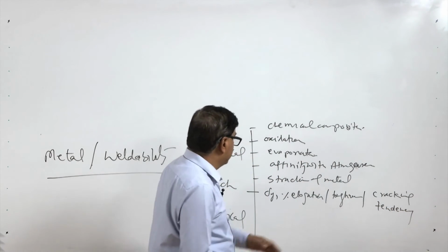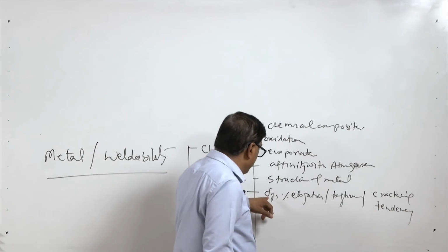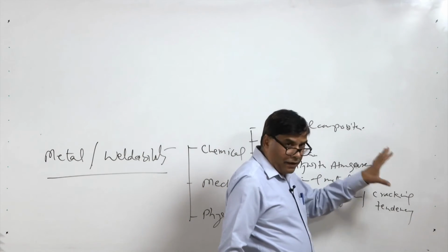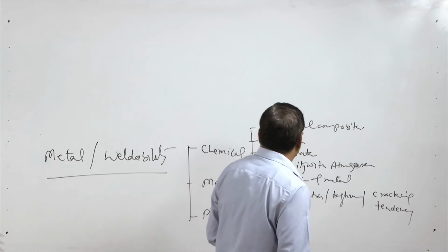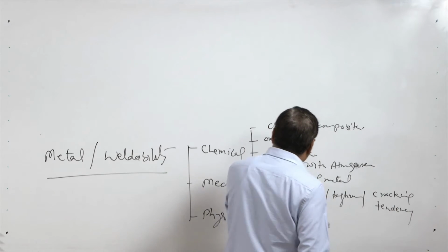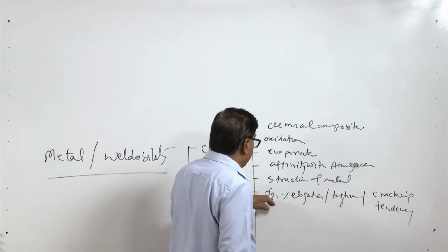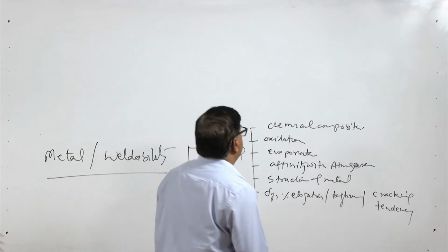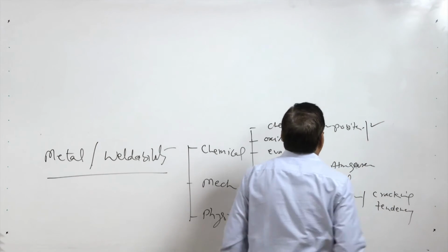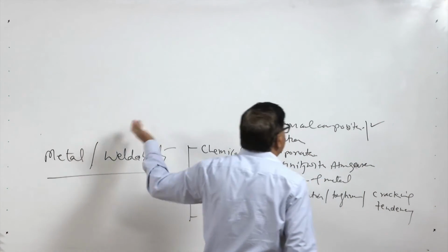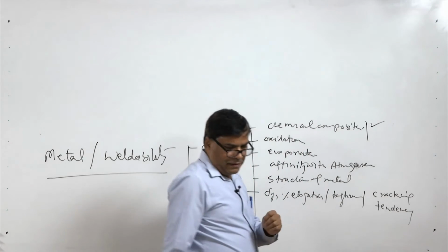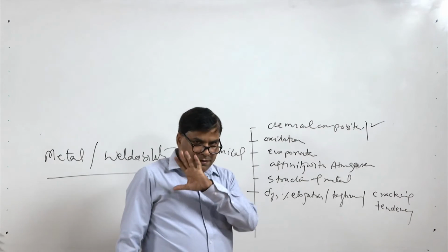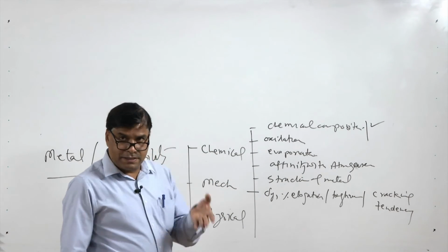High yield strength, low yield strength, higher elongation and good toughness resist the cracking tendency. So, those metals which offer otherwise different properties like high strength, low ductility, low toughness will show more cracking tendency. Similarly, the chemical composition affects the weldability significantly because it affects the solidification temperature range, and it affects the various mechanical properties and physical properties.